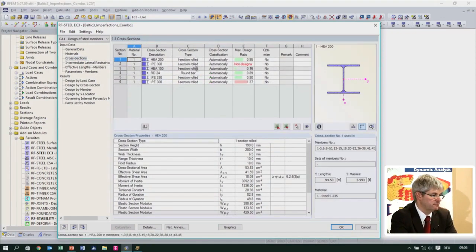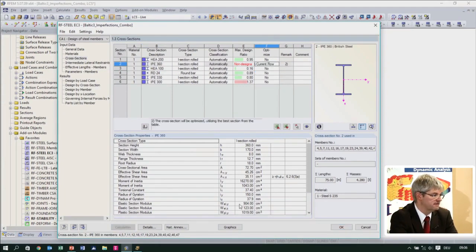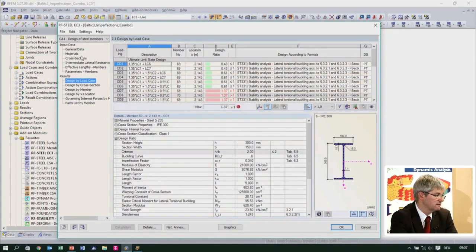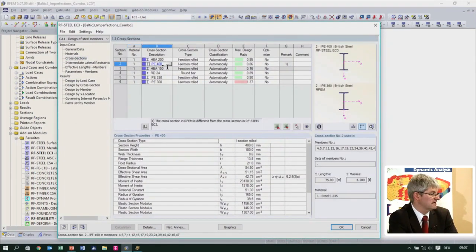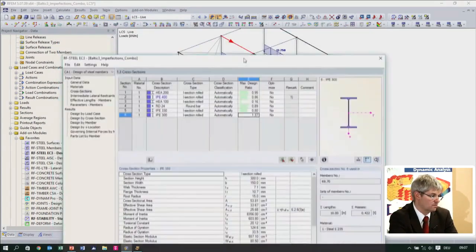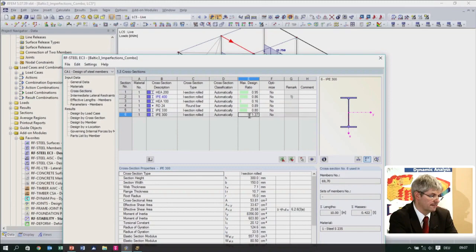So we check here, that is 95, that is 1.73, and because the limit shear stress or the limit torsion portion also depends on the cross section, I can run an optimization and see what type of cross section will be possible to take that torsion. One bigger size will also take care of that. Here, this one is not okay yet. We have to check that also. So let's optimize it.